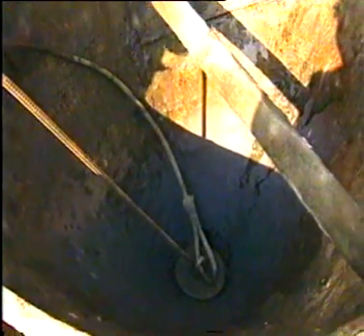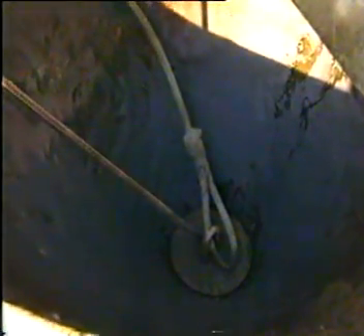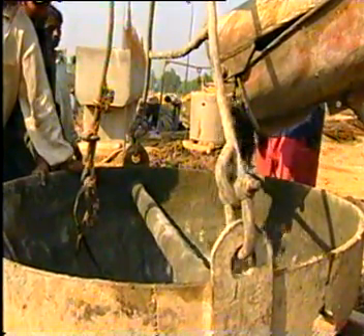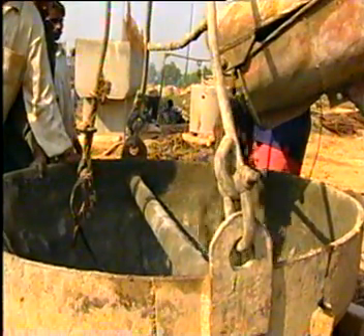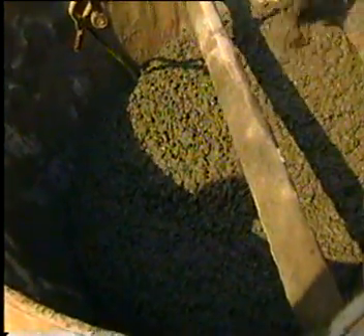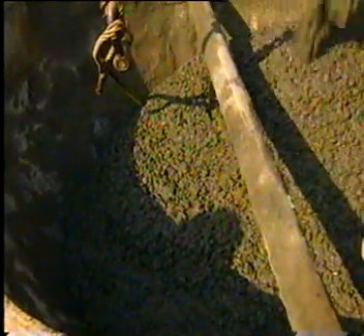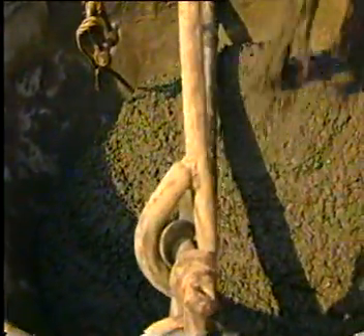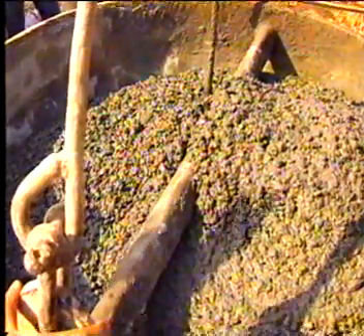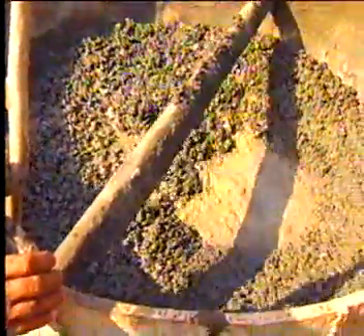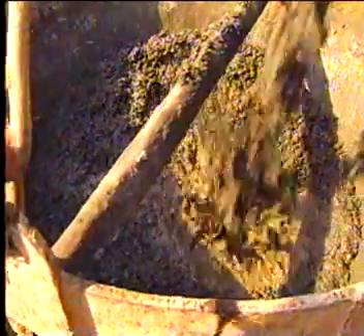The mouth of the hopper connected to the tremie pipe is blocked with a plate and the entire hopper is filled with concrete. The plate is then removed and the concrete is allowed to flow through it continuously. This is done to prevent joints in the concrete all through the pile length.